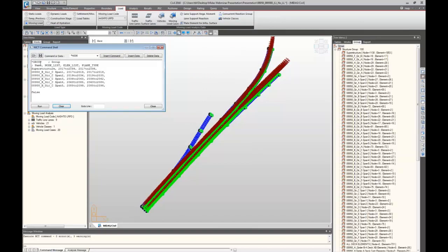It's just a single group command, and then all you need to do is provide your name, so the superstructure group element name, and then you just define which elements are included in that group. And so when you create your macros to define the elements, assuming that you're going in order for the elements, it's easy, if you're defining your pier locations, to also include a group definition because you already know the start and ending element.